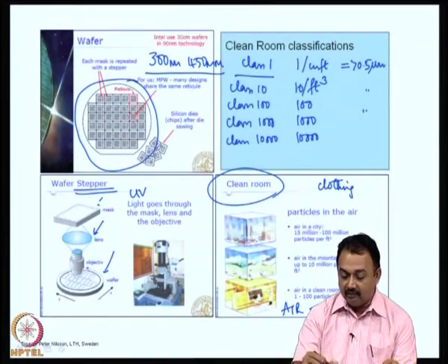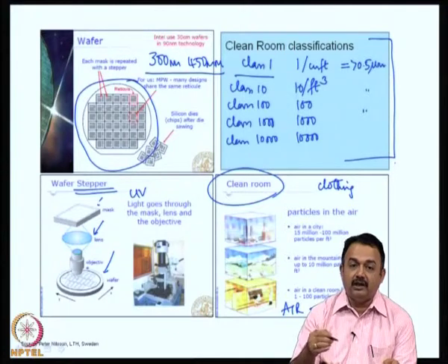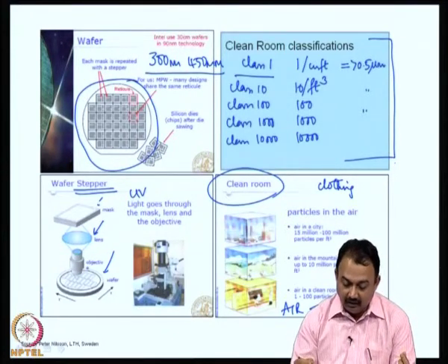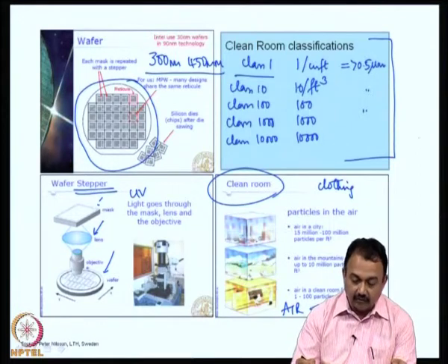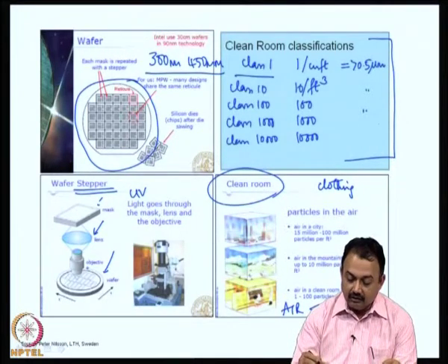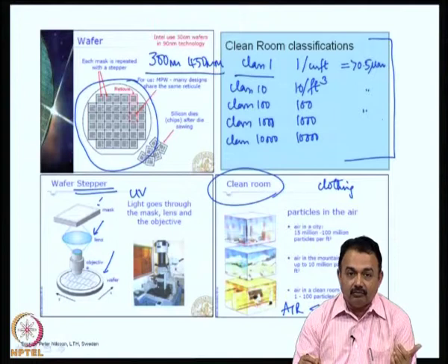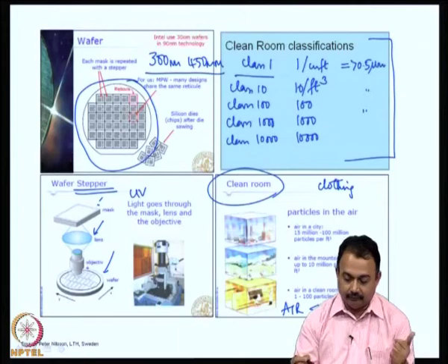So, in semiconductor manufacturing, you can also define for different sections of the equipment processing different classes. Okay. But for imaging, especially the photolithography, you need to have class 10 or class 1 clean room. So, the cost of wafer fab is one side of the coin, the other side is how to maintain your clean room regularly, because any dust getting into the wafer fab processing is going to damage the entire yield equations.